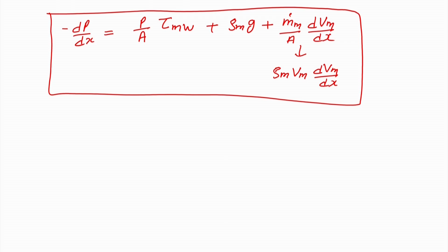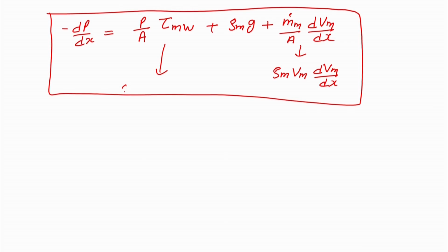Now, you reduced everything in terms of the single phase flow, and because there is no slip, you can easily write everything in terms of the mixture flow rates. Okay. And this tau m is nothing but the mixture frictional term, this is the friction term, this is the gravity term, and this is the acceleration term. Okay, and you are writing every term in terms of the mixture.